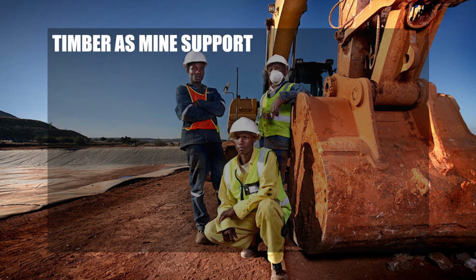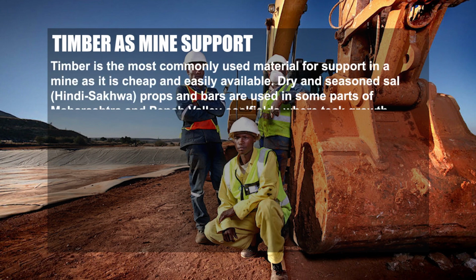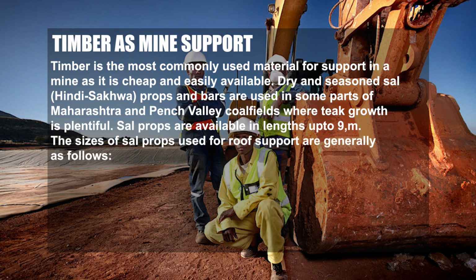So, timber is the most commonly used material for support in a mine as it is cheap and easily available. Dry and seasoned sal and teak props and bars are used in some parts of Maharashtra and Pench Valley coalfield where teak growth is plentiful. Sal props are available in lengths up to 9 meters.